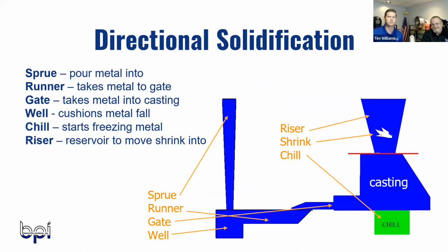And then the last thing was really the directional solidification as well. So again, when we're talking about risers, we're talking about gates. Really, how do you develop out your casting? What's important? Is surface finish important? Is the tensile strength important? Are you okay with some porosity and not all porosity? So really a good instructional sheet to look at here.